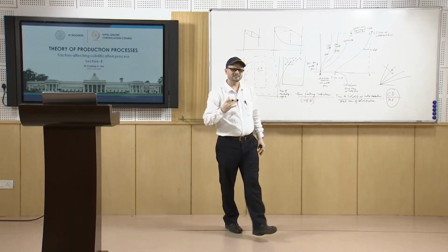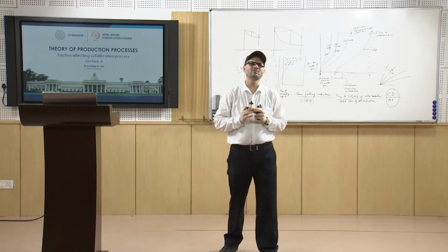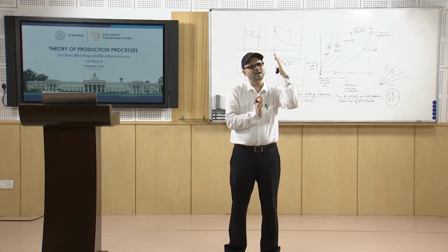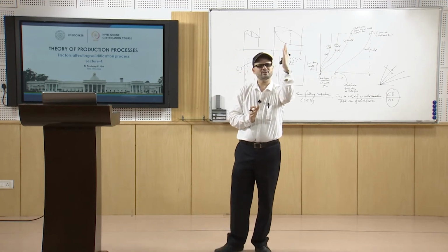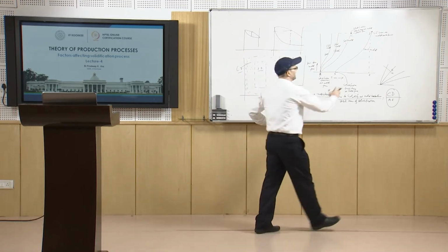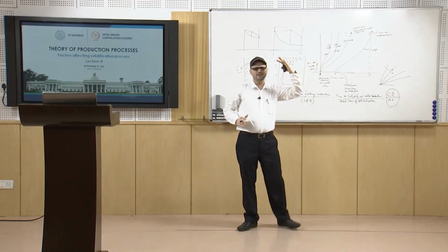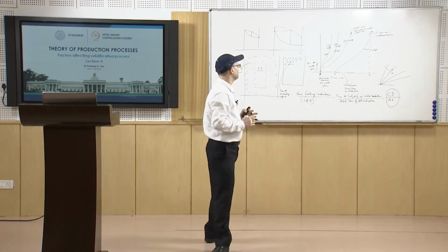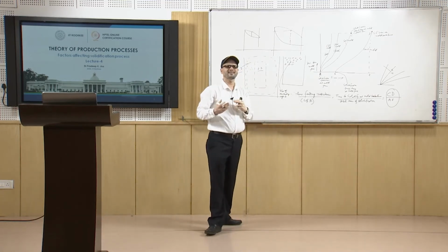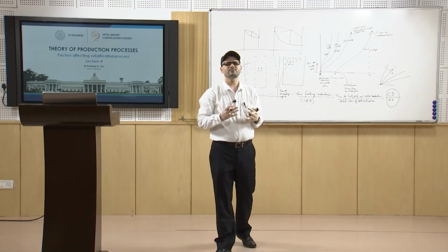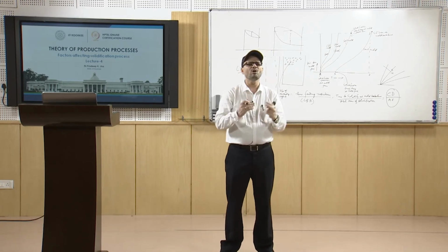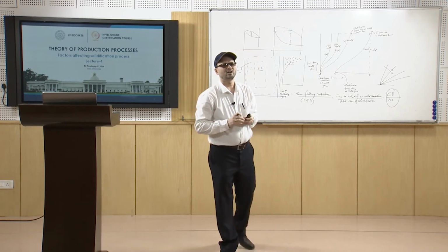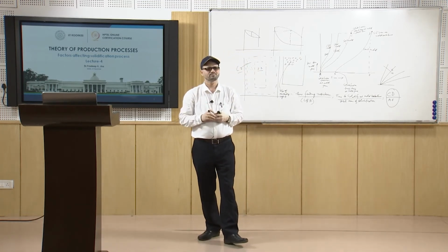In the start you will have formation of the columnar dendritic structure, but slowly the temperature gradient line which we see here goes on getting less and less steep. That leads to the promotion of the formation of equiaxed grains at an early time. So, if the freezing range is more, the ratio of equiaxed to columnar grains will be more.